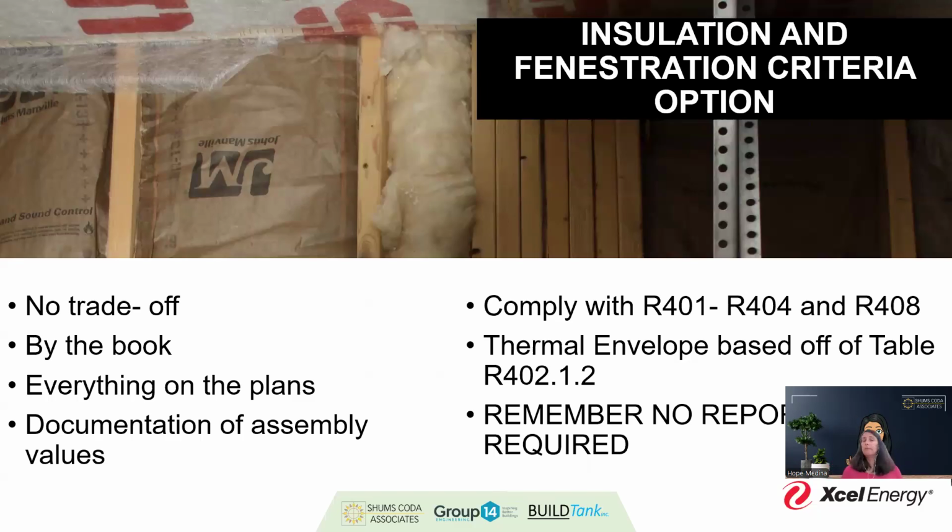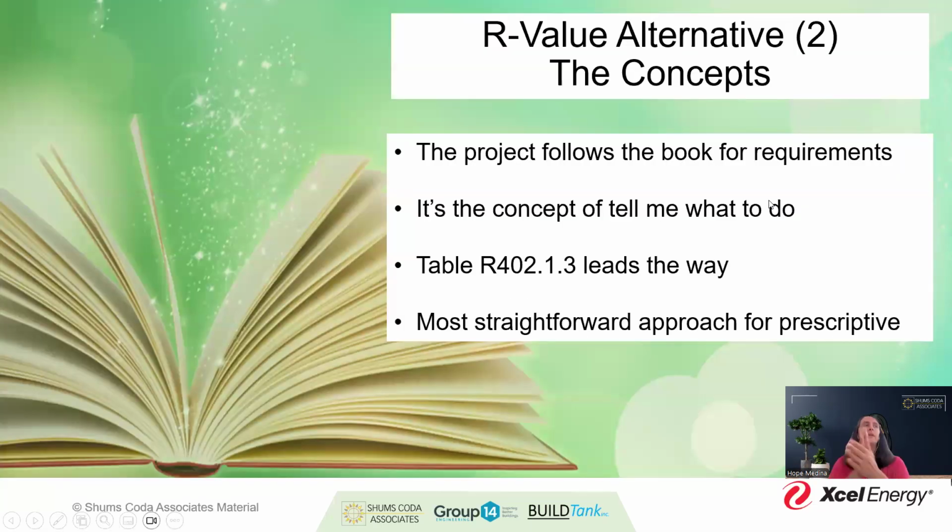Again, with this pathway, you're going to comply with R401 through R404, and you're going to have to do R408 also. The thermal envelope components, you're going to pay attention to table R402.1.2, and there is no report that's required to be provided for this particular compliance path. Now, let's see if we can make it work now. There we go. Now let's move on to the one that we probably are all incredibly familiar with.